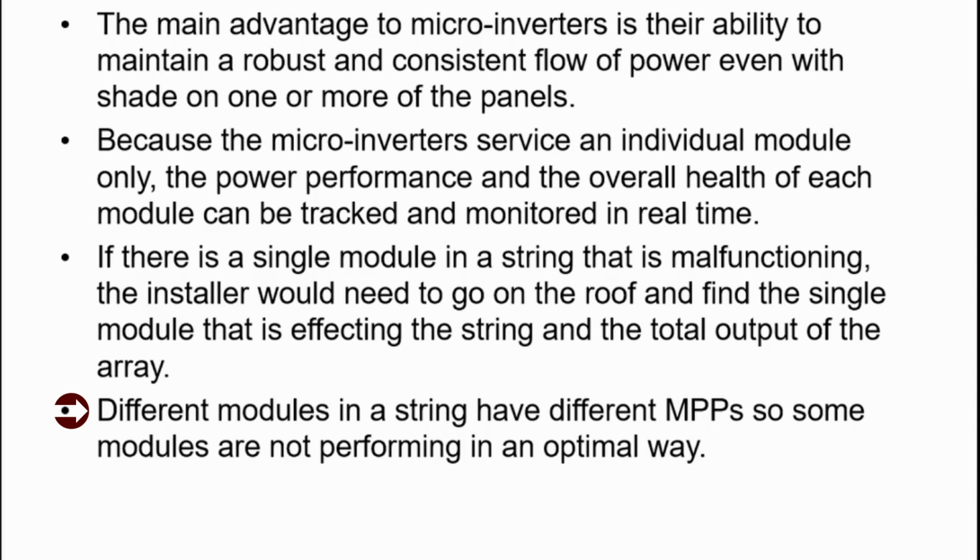Different modules in a string have different maximum power points. This was the other concept you saw before with the SolarEdge concept, where you have a maximum power point tracking device on each subarray. And this is even more true here because you have a maximum power point at each single module.